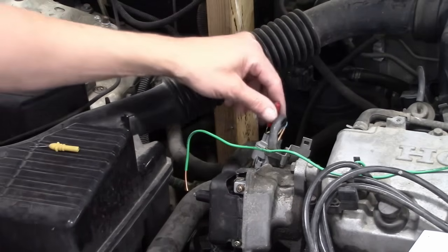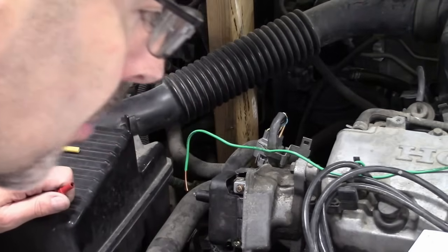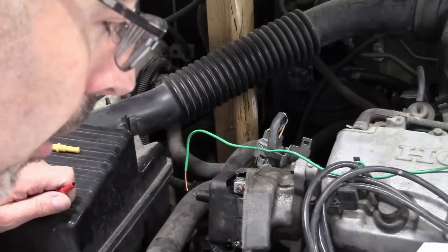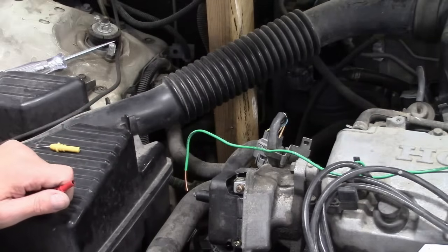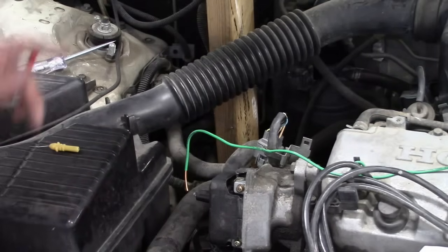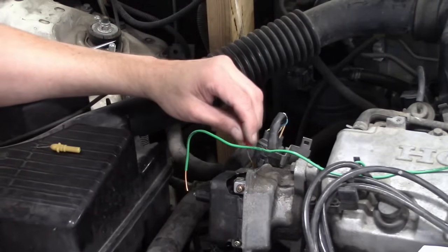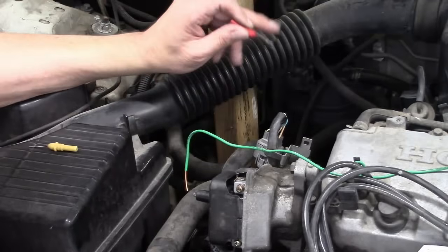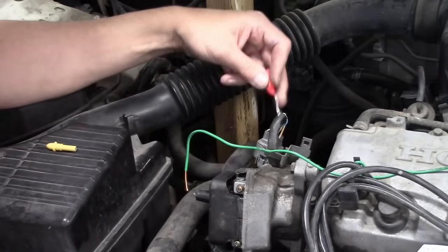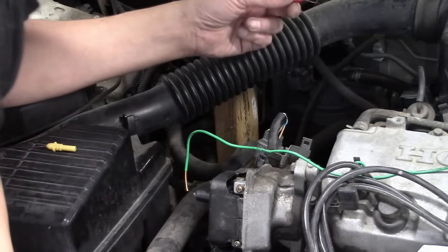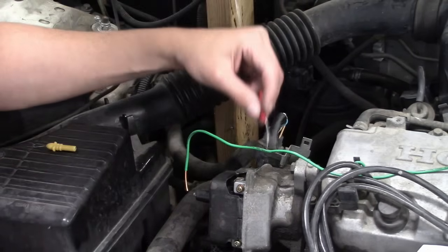So one thing I could do is try to go directly to the coil. So one of the problems, though, is that the coil is ground side controlled through a blue wire, but that unfortunately appears to be internal to the distributor. So I would have to take this apart in order to do that. And that is okay, but I want to just rule out some easier things first.